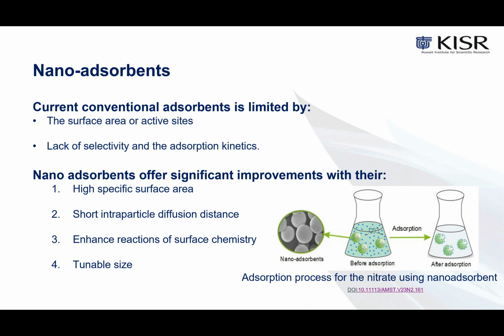The current conventional adsorbent is very limited by the surface area, lack of selectivity, and the adsorption kinetics. So nanoadsorbents offer significant improvements: high specific surface area and short interparticle diffusion distance. It enhances the reaction of the surface chemistry between the toxic materials and the nanoparticles. We also have a tunable size of these adsorbents, which can be controlled in the synthesis procedure.